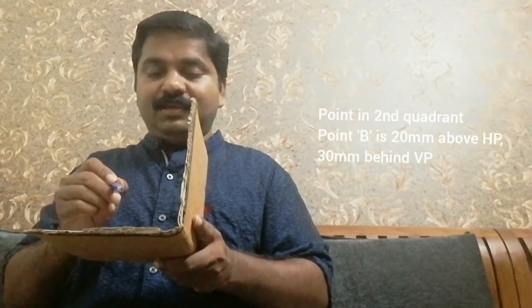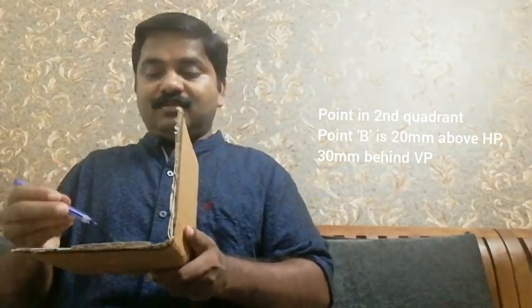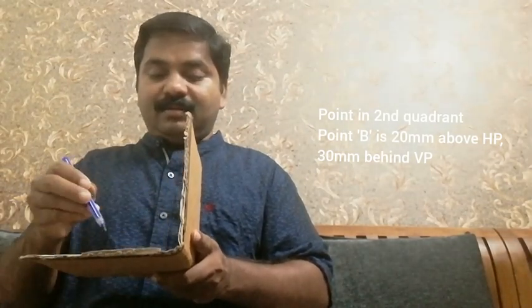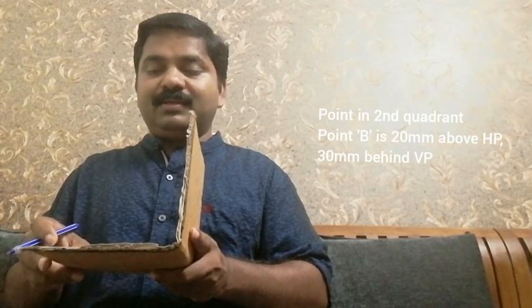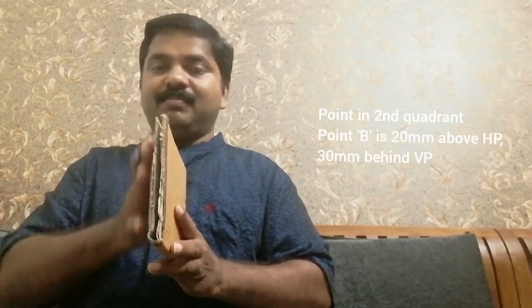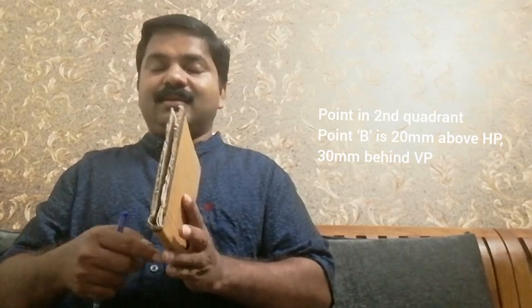Now we will discuss the case of the second quadrant. So here the point is 20 mm above HP and 30 mm behind VP. The person is looking from this direction. So the front view will be obtained here, 20 mm above the XY line, and the top view will be obtained here. This distance will be 30 mm. After having obtained the top view, the horizontal plane will be rotated in the clockwise direction, so that both the front view and top view will lie in a single plane and both will be above the XY line. This is the XY line.